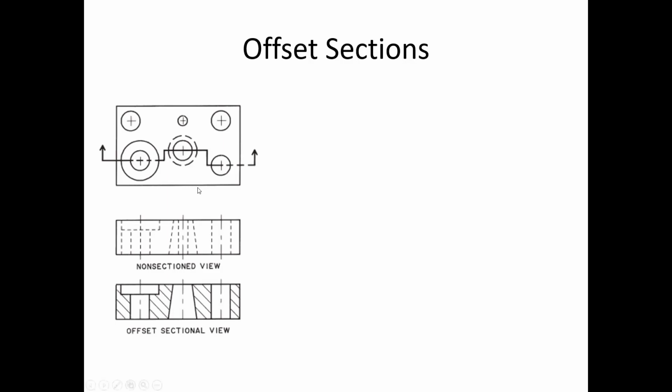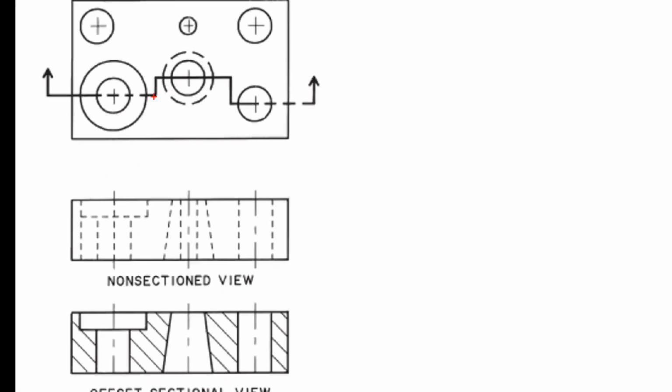And notice where the section view changes direction. Here it turns and goes forward this way. You might be inclined to put a line right here, but there's really not an edge there. So don't include that.